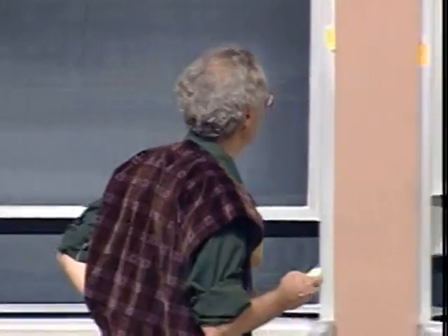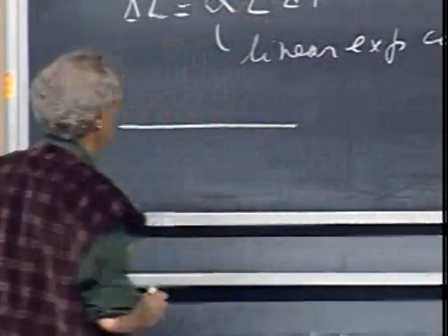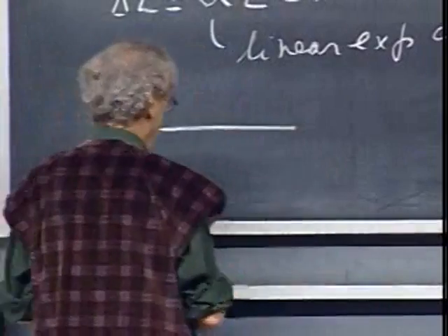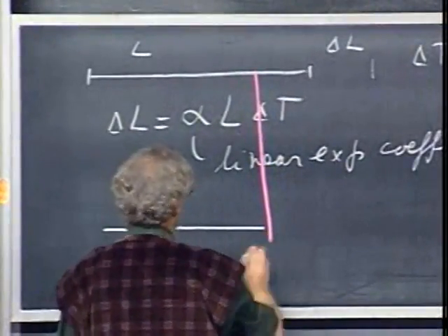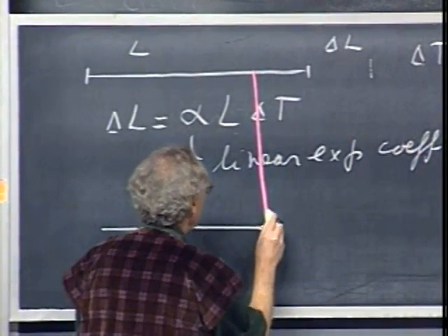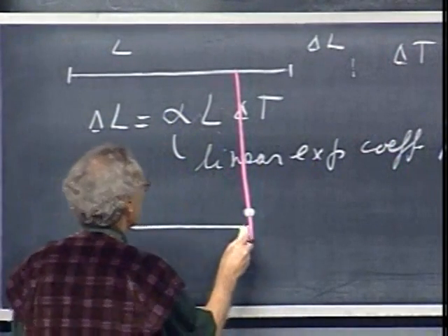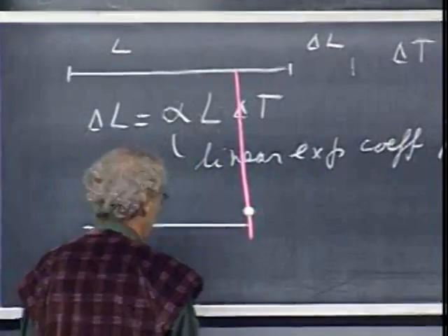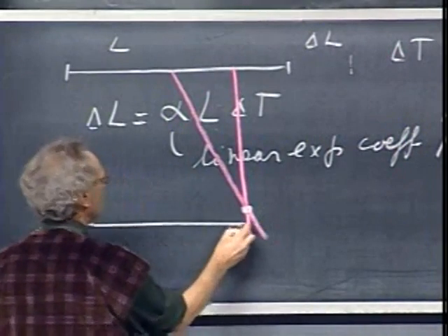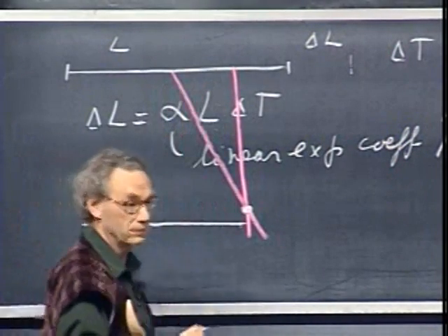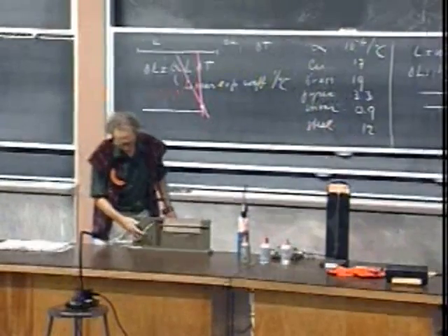The way we do that is we have some kind of an amplifier. If this is the rod, and I would put here a hand, and pivot that hand here, then it's easy to see that if you push against it here, this hand will go like this. So very little extension here will give you a large extension there. We do it twice, so we have two levels. And that is this arm.